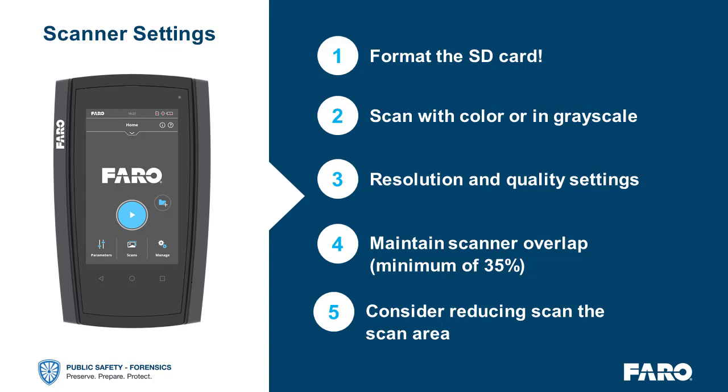I have different recommendations here. I believe that FARO does recommend a minimum of 35% overlap. You may struggle with, what's 35%? What are we talking about in terms of numbers? I've done some other numbers on the next slide, which I'll get to in just a moment. But first, this 35%, I can tell you from experience, having done thousands of scans, is in fact a minimum, and I would recommend moving that up a little bit.